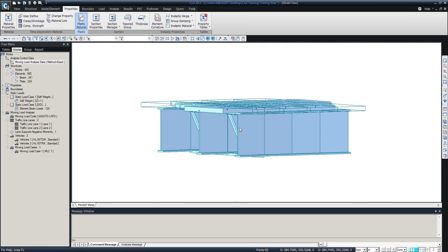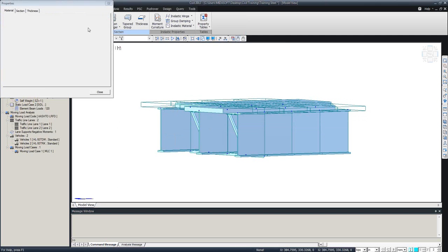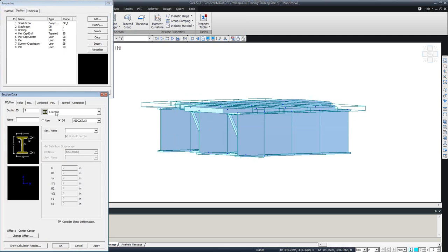Okay. So if I want to have a stiffener here, I can simply go ahead and define a new section, add, and then select this. Let's say 72, and then a thickness of 1 inch. All right, and I call it stiffener.